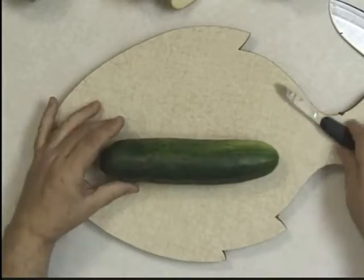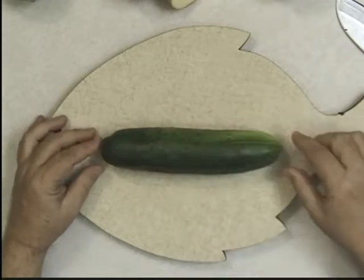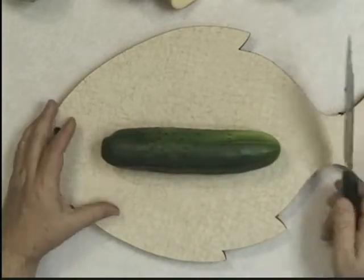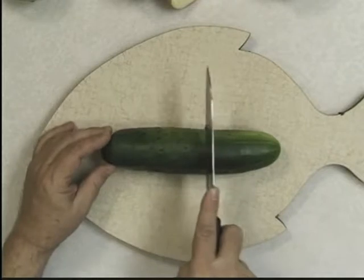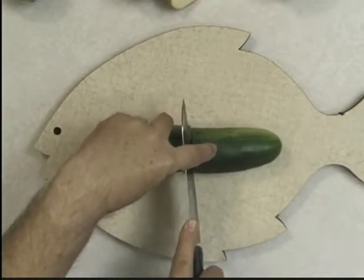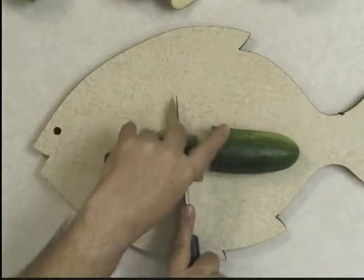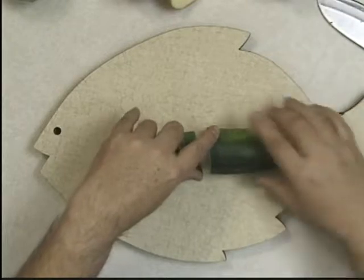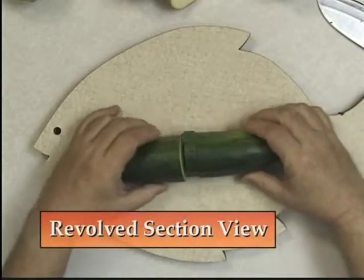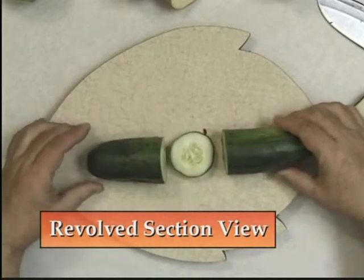The cucumber provides a good example of a revolved section because typically we use revolved sections on things that are long and have a continuous shape inside. And the way a revolved section works is we pick a point for a cutting plane, and we just do this in our imagination, by the way. Actually, we never cut objects. We do it as an imaginary thing, and we draw the views as if they were cut. So we imagine for a revolved section cutting a little place and revolving that part right in place.